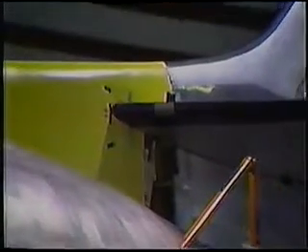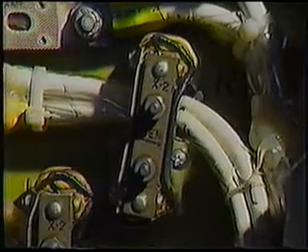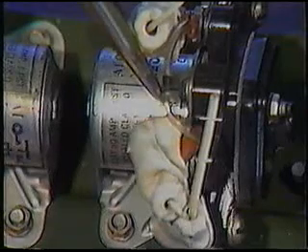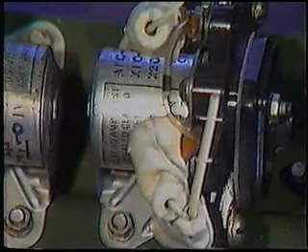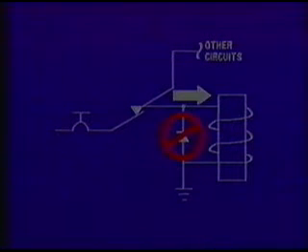Motors, lights, and other significant users of electricity are unaffected, but small voltage circuits can be. Improperly shielded wires are a prime target for these reverse spike voltages to enter and disrupt a normally at-rest circuit, like the fault detection system. The most popular method to suppress these coil spikes is the use of a simple diode. This installation is an example. Current normally flows in this direction. Because the diode is polarity sensitive, it blocks this positive flow of current.